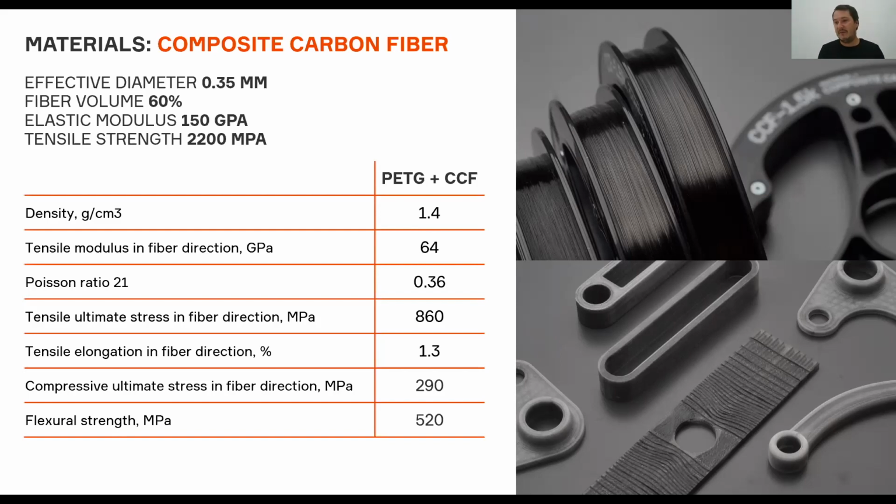The failure behavior, of course, depends very much on the loading conditions, but typically that's the normal behavior of a composite material. If the fiber is properly loaded, then fiber breakage is, of course, the dominating failure mode. And that's what we normally observe in most of the cases.